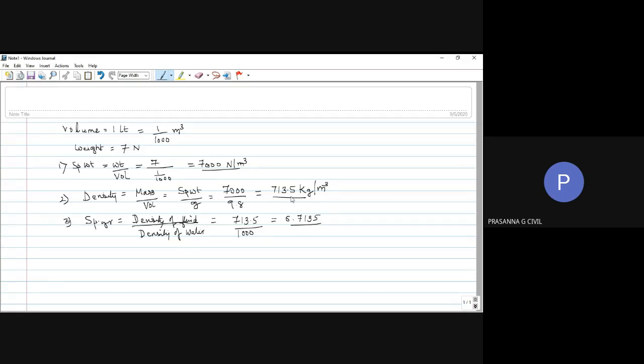So as a recap of what we talked about yesterday, I would just remind you of certain things you can keep in mind so that you do not make mistakes. First, density is mass, so your unit is kg per meter cube. Specific weight, when that weight term itself comes into the picture, you should think about Newtons only, so that you have the unit in Newton per meter cube. And when we say specific gravity, always study it as the definition of a ratio.